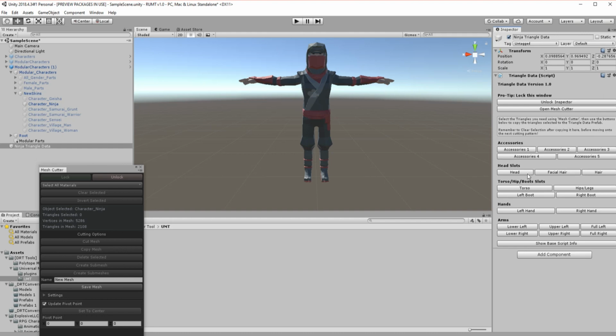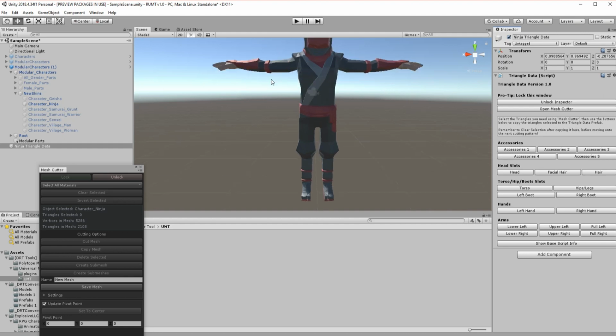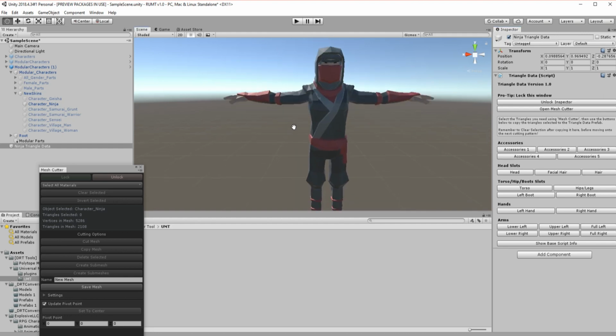Special rules on the other parts to check. So, for example, if you cut the head and the torso, it's going to check for what parts here are shared for the vertices, and it's going to fill them in. If you cut the head but not the torso, it's not going to find those things. You're going to end up with a hole in the neck, which, if everything lines up nicely with your models, probably won't matter. But it's nice to fill them in just to not chance weird lights getting into them and stuff like that.